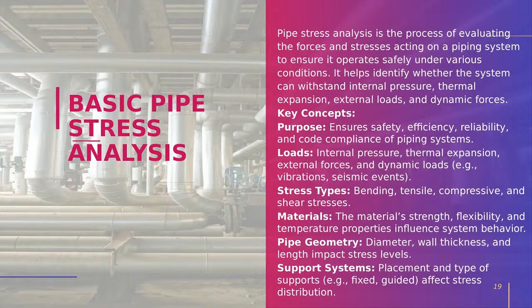Generally we follow API 610 for centrifugal pumps. In that case, it was a special pump made up of a different MOC other than carbon steel. So there we faced a major issue. The client simply didn't accept our general arrangement and isometric drawings. We had to come back to the stress analysis and do rework. We brought the allowable limit back within the manufacturer's code. Then we cleared that project.